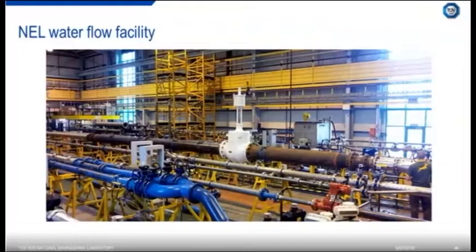Once you've decided to test your valve, you obviously need a flow facility. So NEL's water facility would be a good choice. This is an example of a globe valve being CV tested in the facility. You can see the upstream and downstream pipework. As NEL, we're the holders of the flow measurement standard for the United Kingdom, so all our test rigs are fully traceable. We're actually the primary standard, so everything has got low uncertainty, which makes us perfectly placed to perform CV testing.